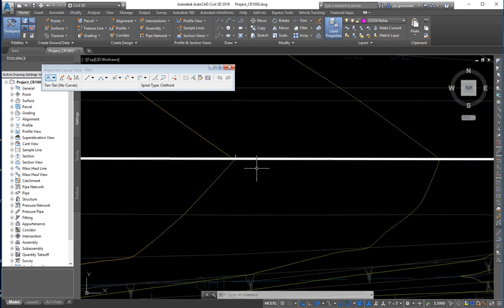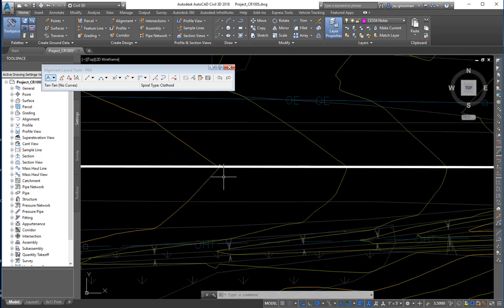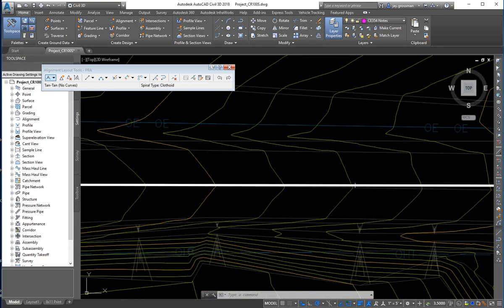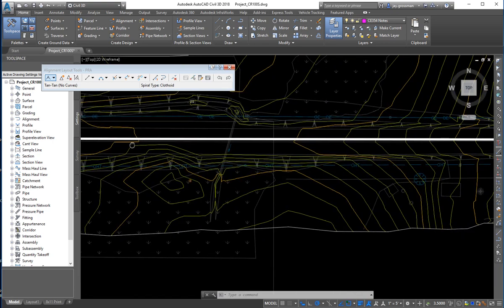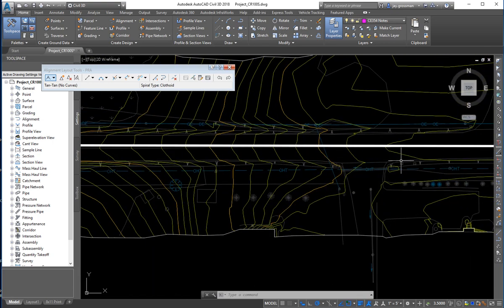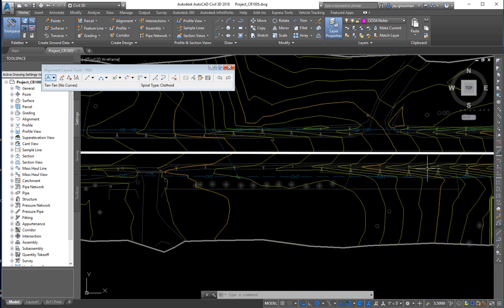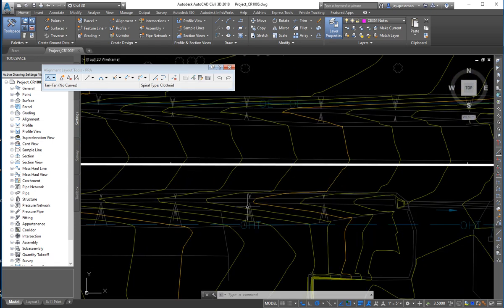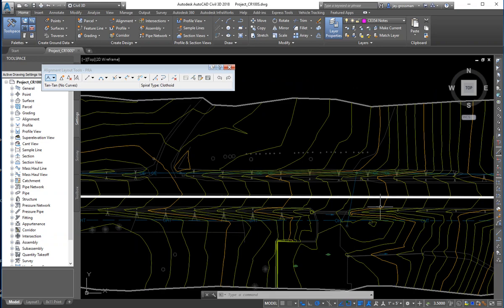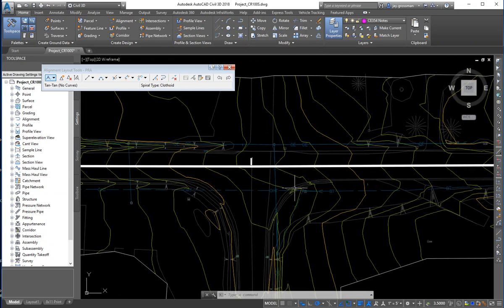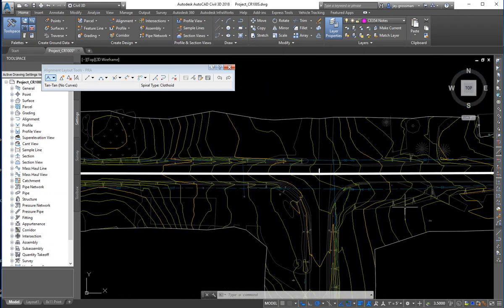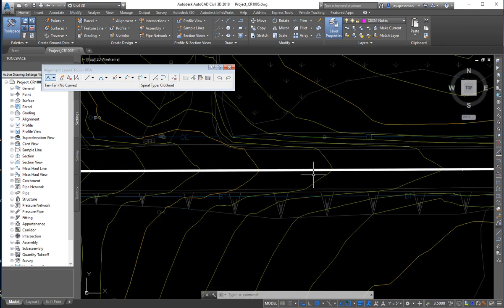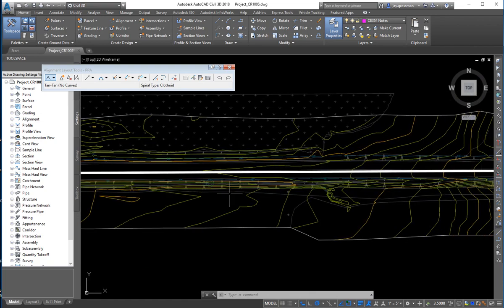So we're going to zoom in here. I'm not quite on the center line of the road. There, I'm not too far off. It's close enough. The existing center lines of roads wiggle around. They probably aren't following their original alignment. And there was a little wiggle. That one went pretty far off. It probably scooted over because there was a house here back in the day when they were working on it. There's that. So we can put in a vertical curve. We can put in some PIs there if we want to arc it.